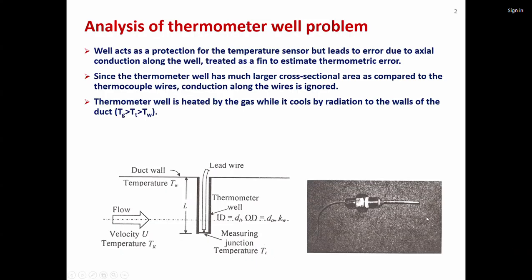So this is a typical thermocouple arrangement that we do when you are trying to measure temperature of the fluid. So this is basically the thermocouple tip. This is the thermocouple wire, which runs like this to the data acquisition system. So you create a well sort of thing in the tube, and with some thread, this basically goes, and you can tighten it here, and it just is held in place.